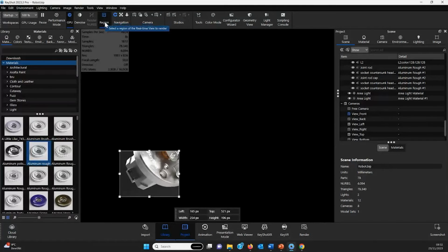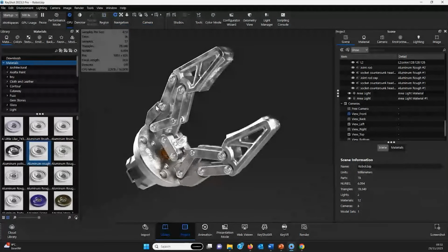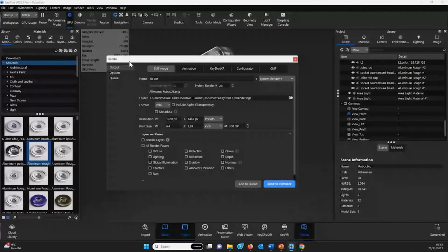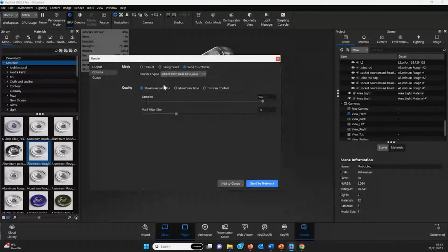That then is the amount you can use for your final rendering. So just switch region rendering off again, switch to your render settings, to the options, and you can type in the samples you found out were perfect for your rendering. Also, if you notice that you need a lot of samples and maybe do not have the strongest render machine, it is also recommended to use send to network if you have network rendering as well.